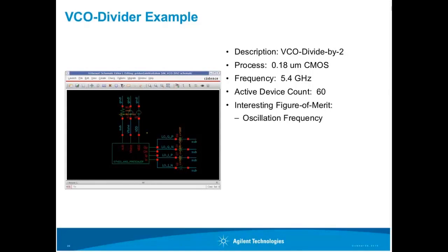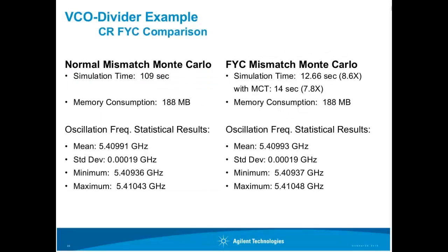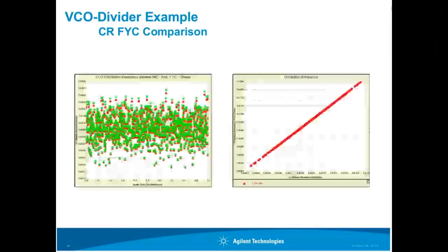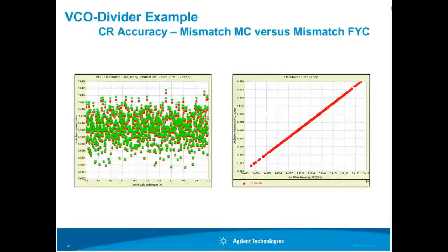We also have this additional parameter called correlation, and that takes into consideration the fact that there may be other parts of the circuit which are designed to cancel that out. For instance, you may have a bias circuitry which has a matched transistor in a different block from a load circuit that is designed to swallow up variation.